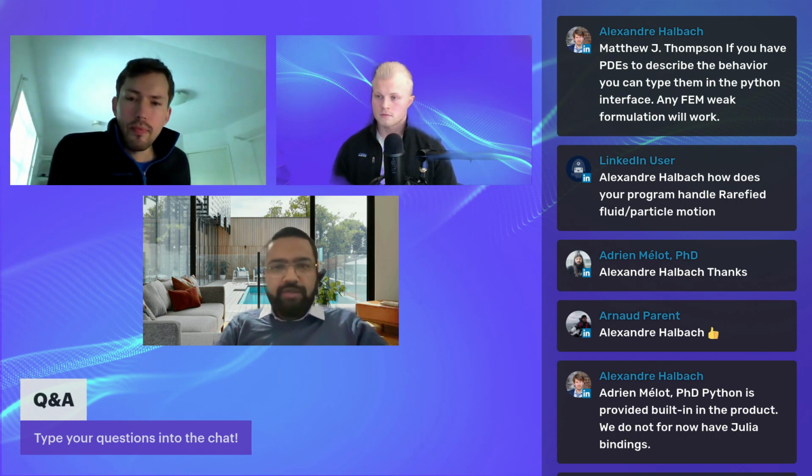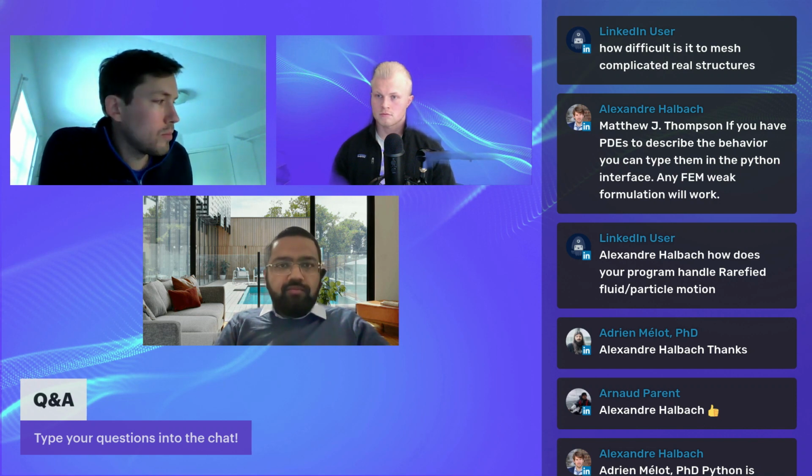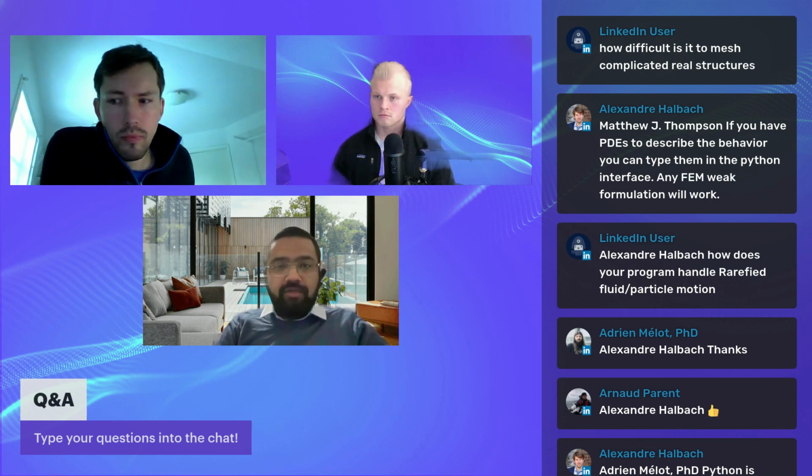For the joule heating, it wasn't the case, but for this case, we had to include mesh deformation, and that's the reason I had to additionally implement this in the scripting. But in future, we are going to include that also in the GUI, so there should be no problem in the very near future. But that also highlights the advantage, or the power of Python scripting. So if you want to do something non-standard, it's quite, or I won't say easy, but it's relatively easy to implement if you know the equations in your finite element weak form.